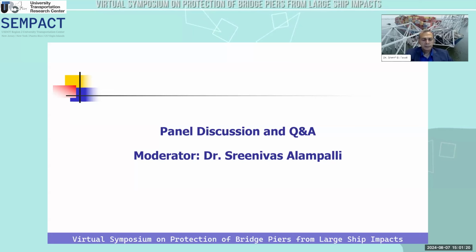Yeah, this is Mike. So it's a few comments. One is that I think the way forward is the first solution should not be to design the bridge to withstand an impact from large ships. We need to be looking at longer spans over the waterway. In the guide specification, there was a section on planning for new bridges, and it suggested that as a minimum, new bridges should be 2 to 3 times the length overall of the design vessel or largest ship in the waterway.